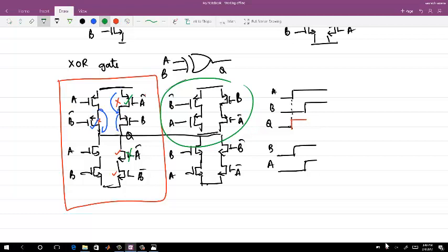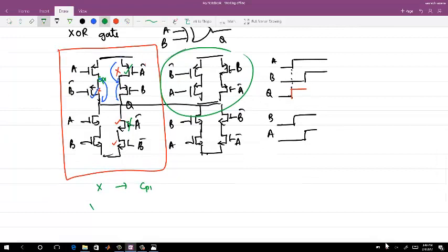I have only, let's say, the first part, and I have CP1 here. When it was X, the intermediate node was CP1. So when I break into X by 2 and X by 2, if you still maintain CP1 and CP1 at both the nodes, then I think it will be slower. So this comes to the layout.